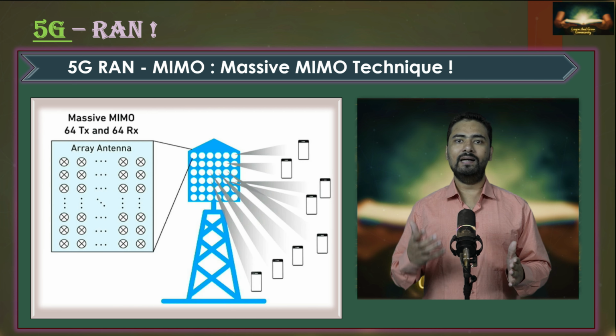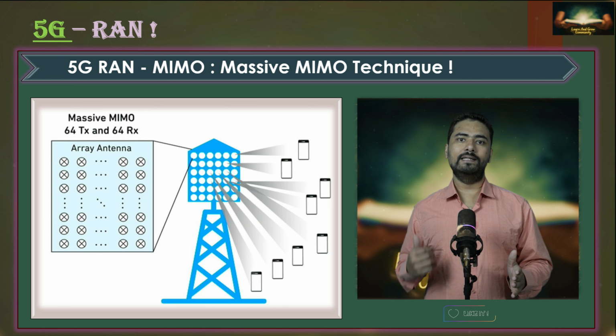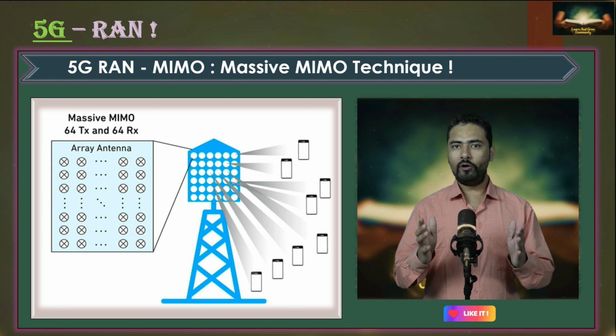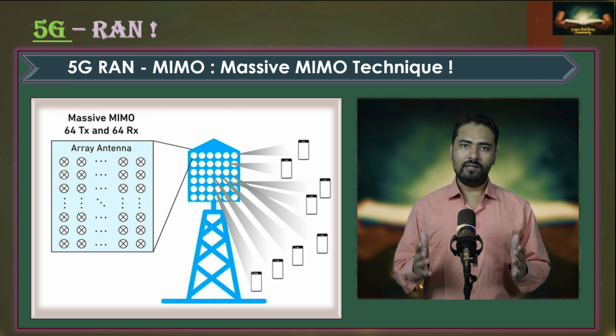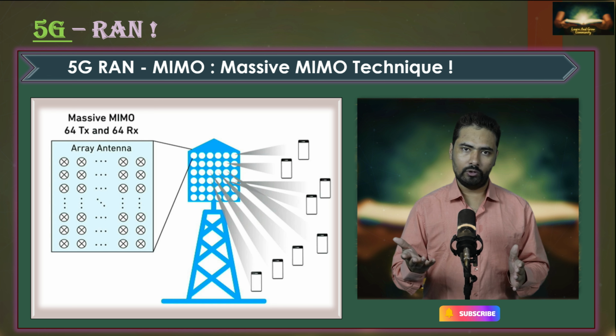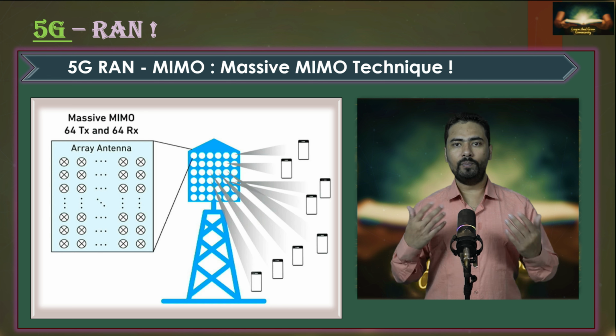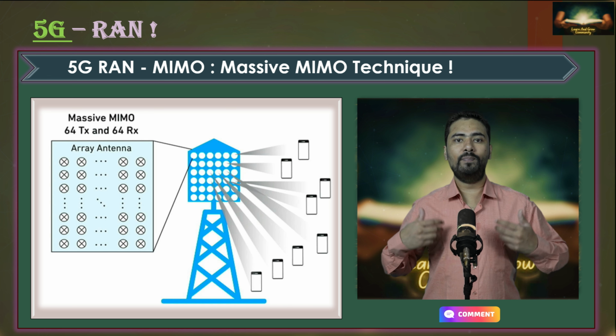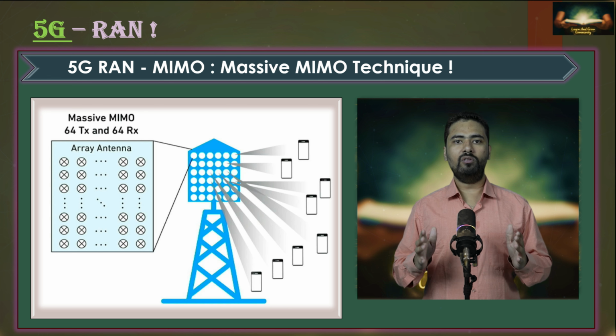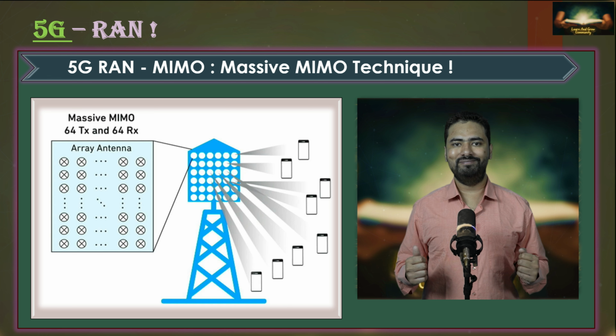Beamforming enables the concentration of power towards a specific spatial region or a specific UE. So you see in this picture here. As a result, now the scheduler has an additional responsibility because now it has to plan not only the time domain and frequency domain, but also the spatial domain. So this is how beamforming works in 5G.